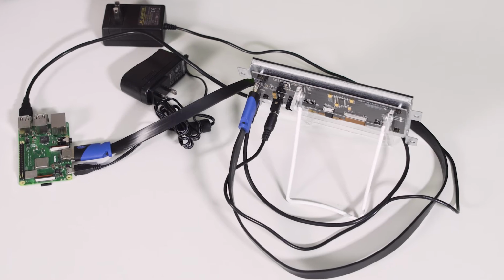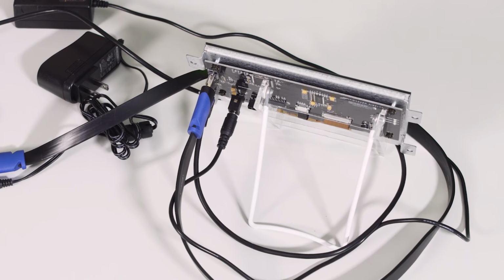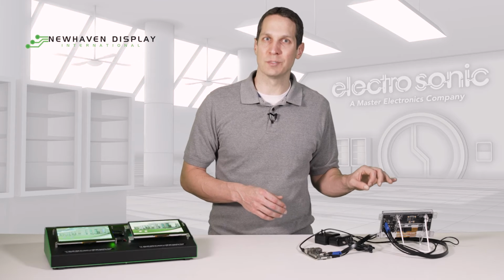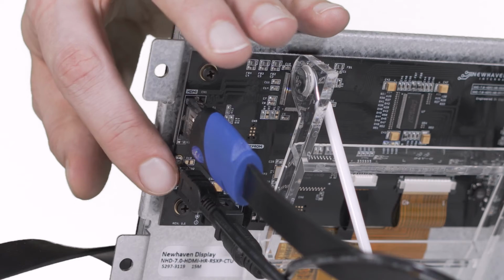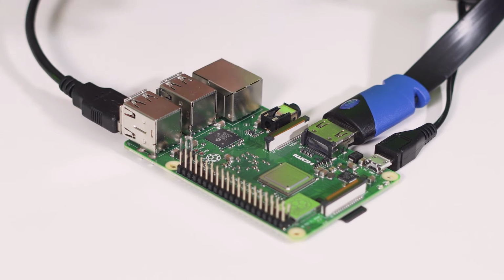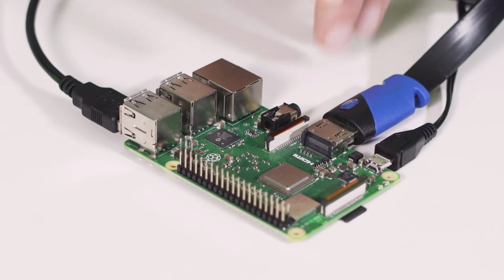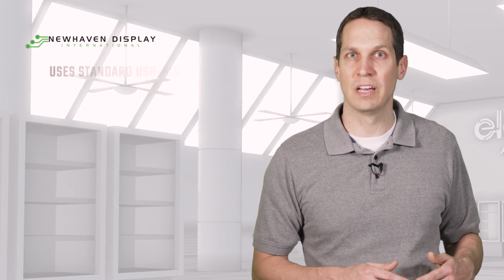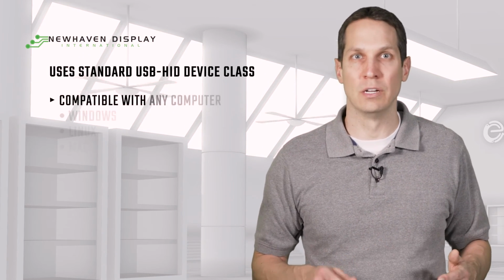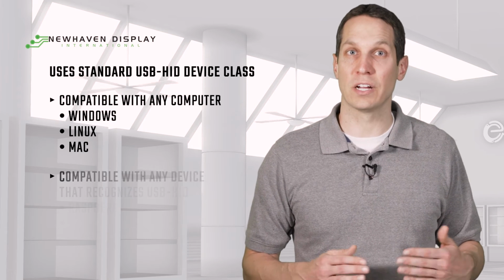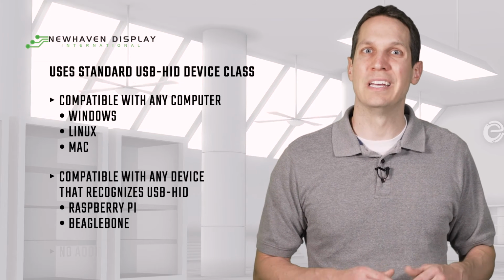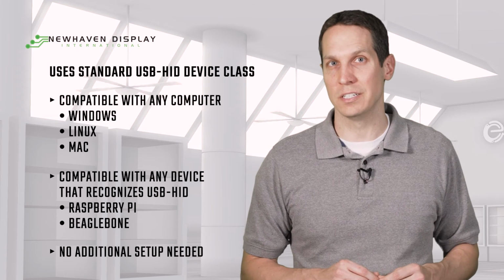As you can see, using either Newhaven Display's TN or IPS HDMI display, it is very easy to get up and running. This is a 7-inch HDMI IPS TFT display, and all we need is to provide power, connect the USB to the device that is driving the display, in this case a Raspberry Pi, for the capacitive touch feedback, and then the HDMI connection between the display and the device. This uses the standard USB HID, or Human Interface Device, class, which means that you can plug the USB into any computer, Windows, Linux, or Mac, or any device that recognizes USB HID, like the popular single-board computers Raspberry Pi and BeagleBone, and it'll work without any further setup or driver installation.